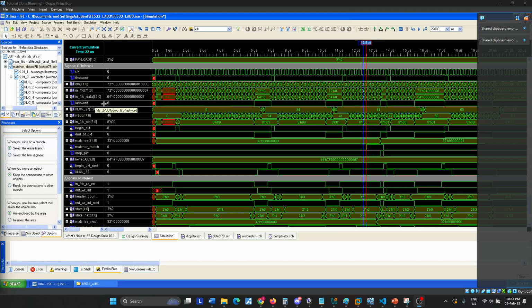One observation we need to make here is that there is a gap and a delay of 3 packets before my input FIFO packet starts actually matching. So if I take the cursor here, you'll see that this particular data will get updated here after 3 clocks.